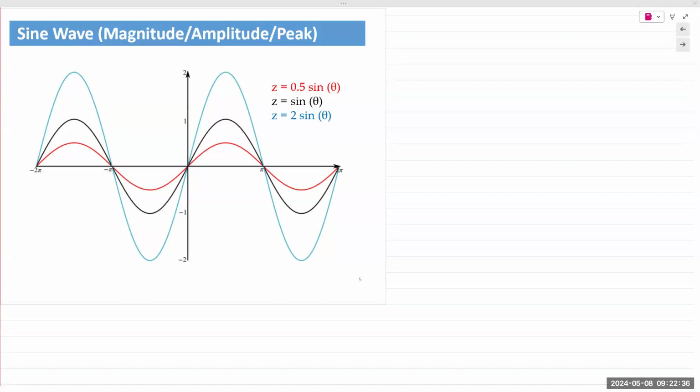So what is the power outlet rating? Online students and in person. I stated this on the first day of class. Some murmurs of about 100 approximately. So in North America, it's 110 or 120 volts. And frequency, anybody? 60 hertz. Outside of North America, it's anywhere between 220 to 240 volts and 50 hertz frequency.